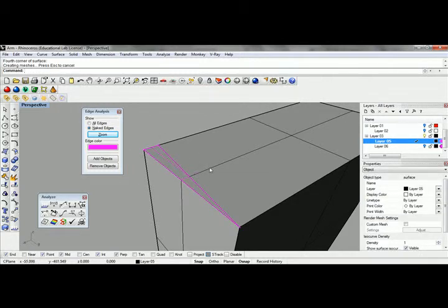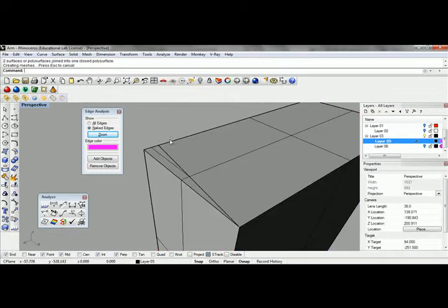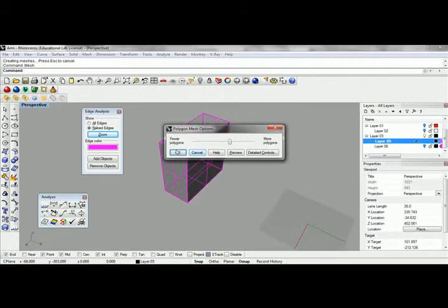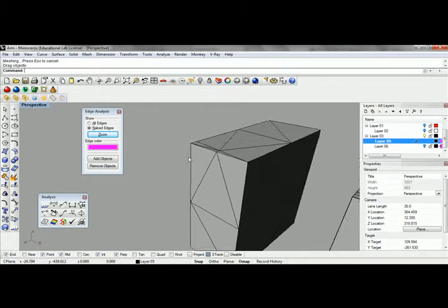So we created this surface, and we can create all these edges and triangles, and we're good to go. You'll note that up here it says these two polysurfaces were joined into one closed polysurface. That means that we're in good shape. And so now we can take this and mesh it, pull that out, and we now have a good object that we can take to the printer.